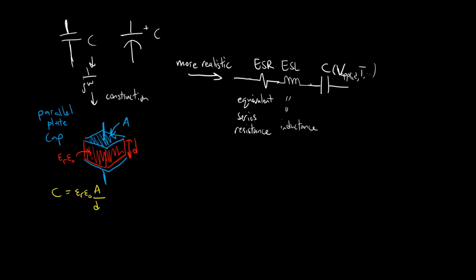And then finally, this dielectric might not be perfect, an imperfect insulator, which means some current might flow between the two plates, right? And we kind of model that with, I'll use a dotted line, a resistance in parallel with all this stuff, right? And this you might call the leakage resistance.